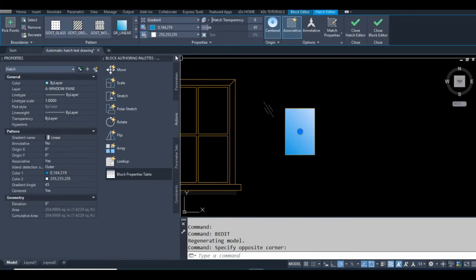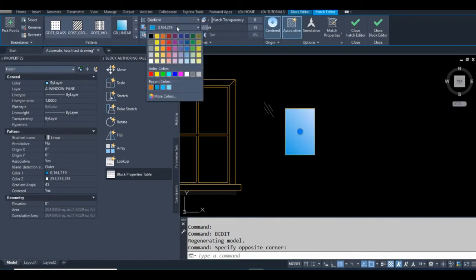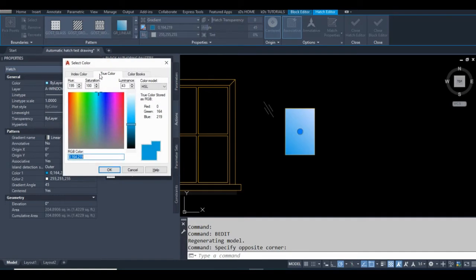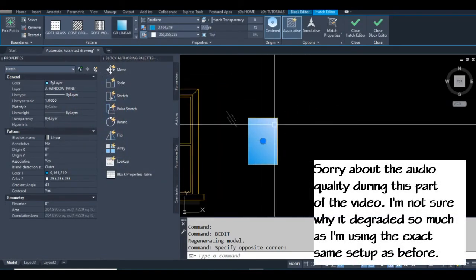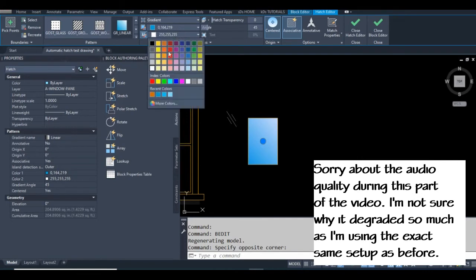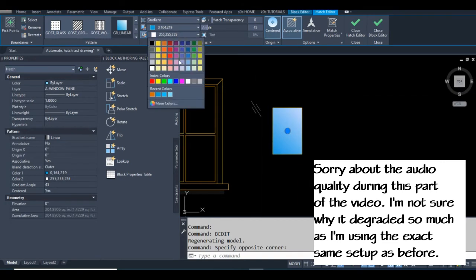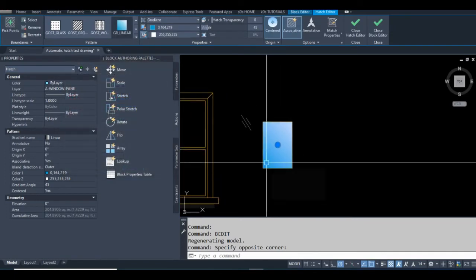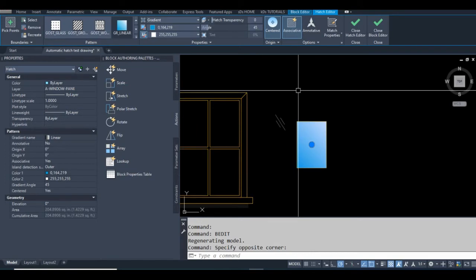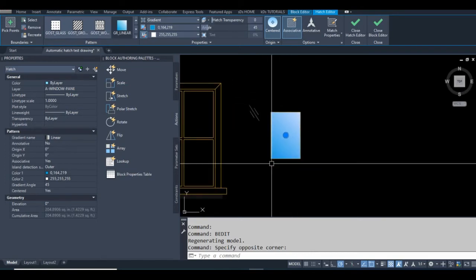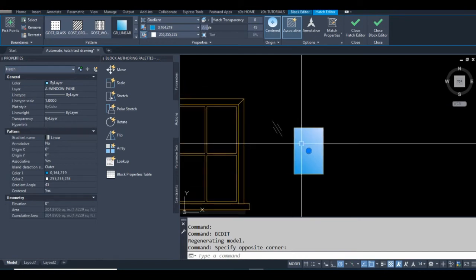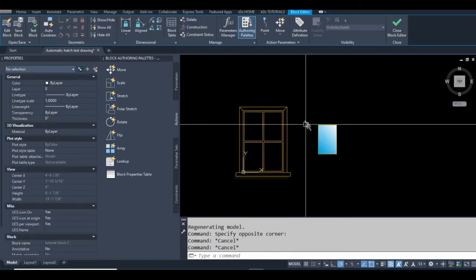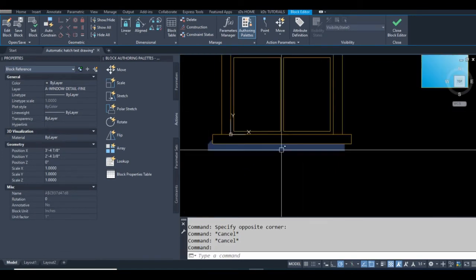Okay, so with this hatch, it's just a gradient, and I've picked 2 true colors for each color of the gradient. Now the white is actually color 255, 255, 255. If I make it color 7, the index color 7, it'll just print black. That's not quite what we want. If I use the true color value, that's the color it'll actually print as. So it ends up being a gradient of this light blue color, and it basically fades out to the paper color. So I have these little window streak marks that I've made, and the shadow down here.